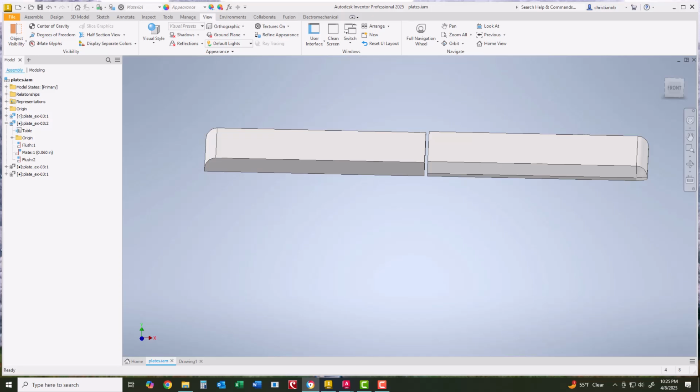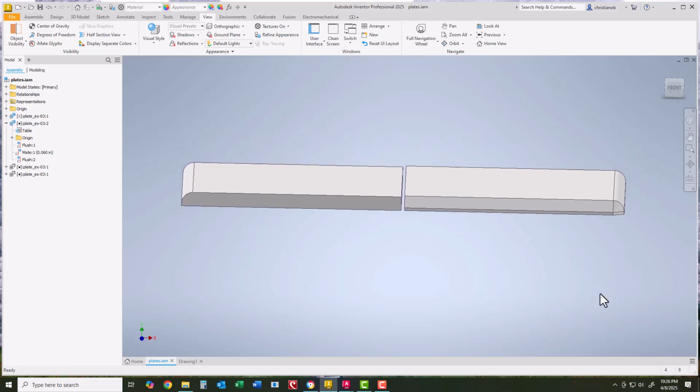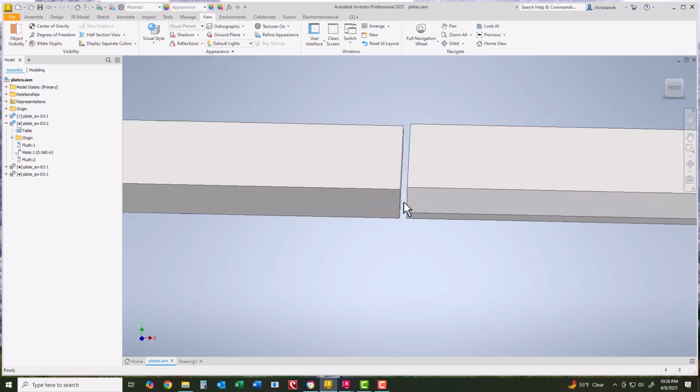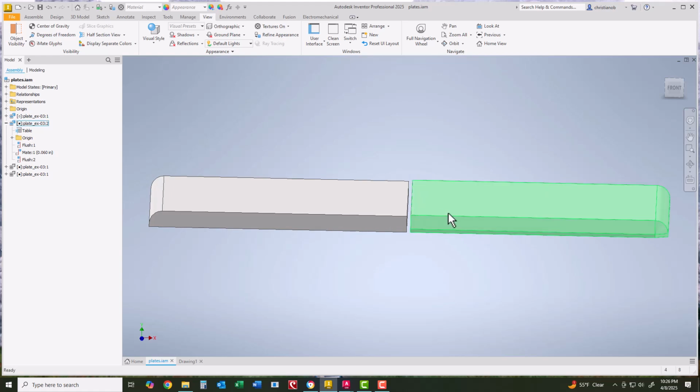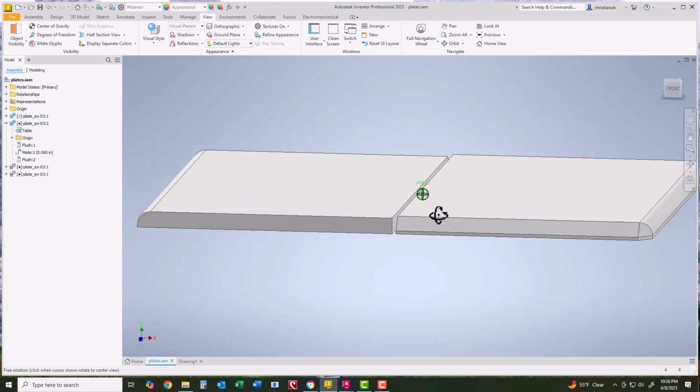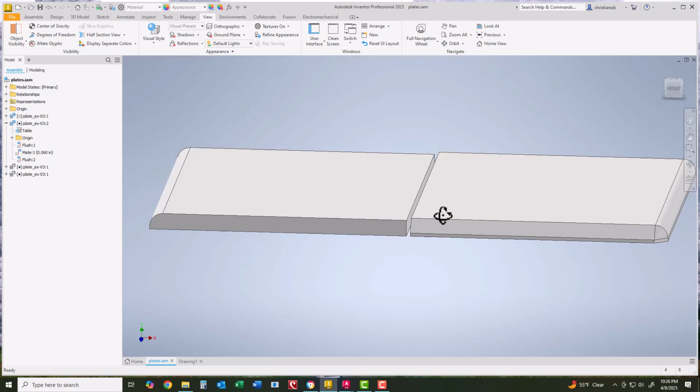and if you look at the weld symbols, that's the square groove weld or the butt weld, and that's a typical, you've got to have a space in there for the welder to be able to weld it. So it's got to be a small space. Can't be too big because then it'll not be an effective weld. So the spacing on the plate when he goes to weld it has to be a fairly small open space for him to weld a square groove weld.